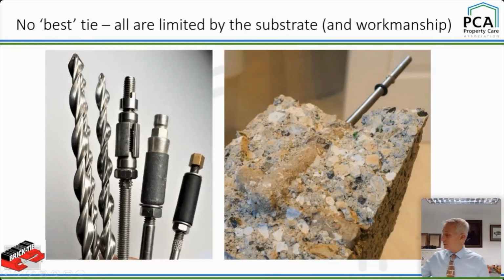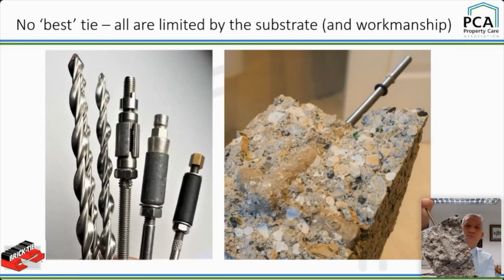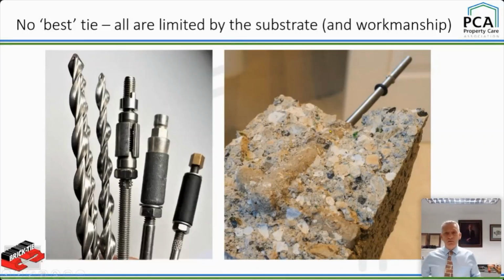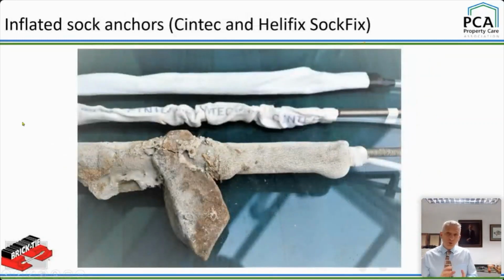And there we've got a resin bonded tie. Actually, there, wave that at you. See, look at that. It's great, that, because we've broken that open to show how they work. You fill the hole with resin and then you put your tie in, and basically that holds it all together. And from the point of view of bearing stresses, what you want is to spread the load.